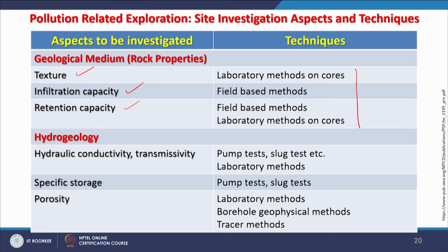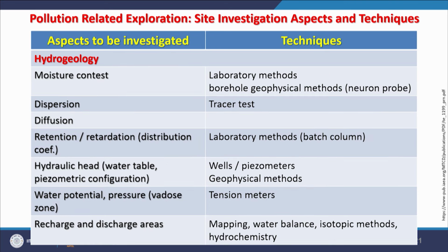Then hydrogeology, which includes hydraulic conductivity, transmissivity, specific storage, porosity, all those basic hydrogeological parameters or characteristics of these aquifers are required. And similarly, moisture content, dispersion, diffusion, retention, water potential, recharge and discharge sites. This I have been mentioning about. This is very, very important.